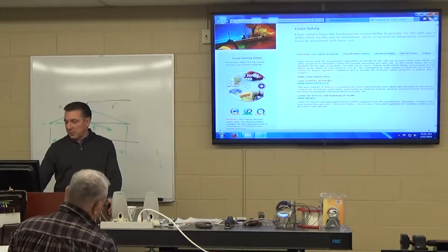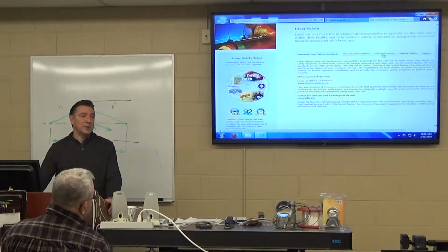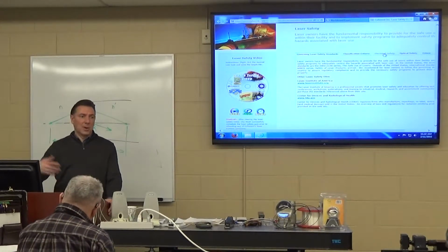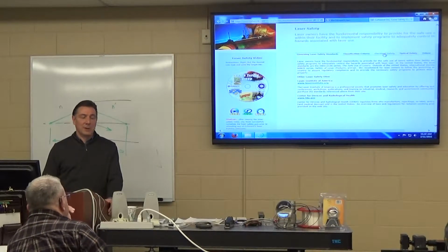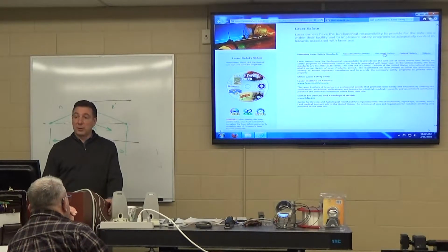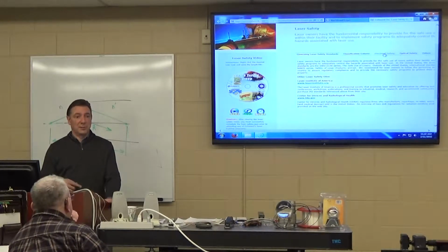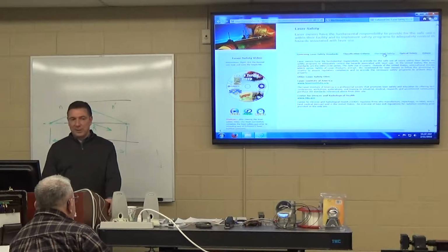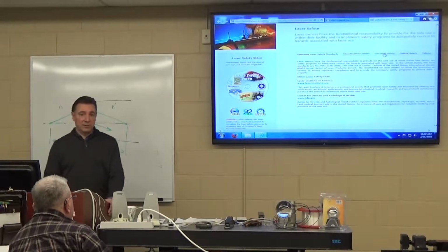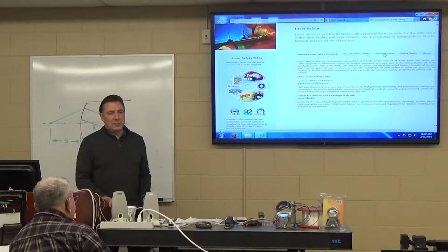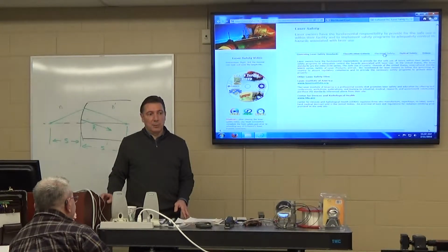One of the other things I wanted to point your attention to is they also have an electrical safety component to this. A lot of times, you're thinking you're working with lasers and it's the light that's going to hurt you. Well, a laser beam could burn a hole through you. The good thing about a laser beam is that if it burns a hole through you, it also cauterizes as it goes through. So your chances of survival are much better. But most of the accidents that have caused death in the laser field are caused by electrical problems. Most lasers, and especially industrial lasers, use very high voltage power supplies. And if you're messing with the power supply, you have to know what you're doing.